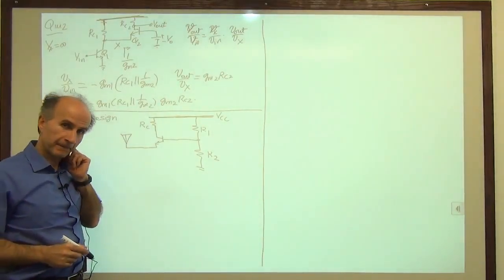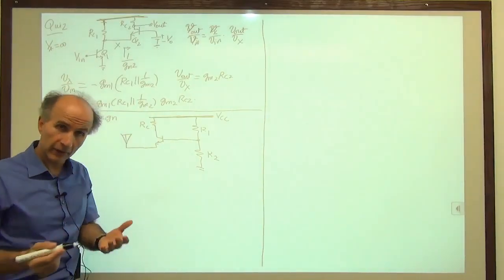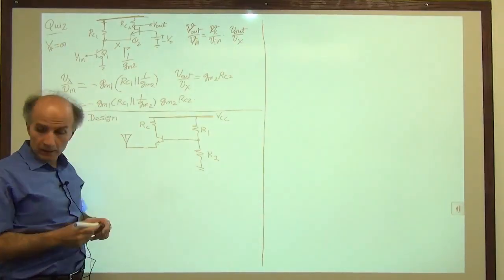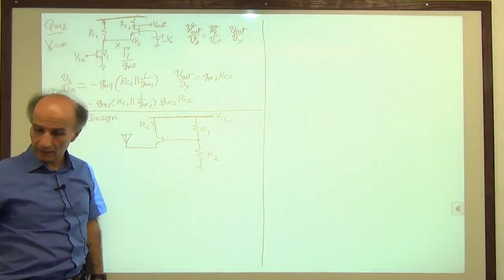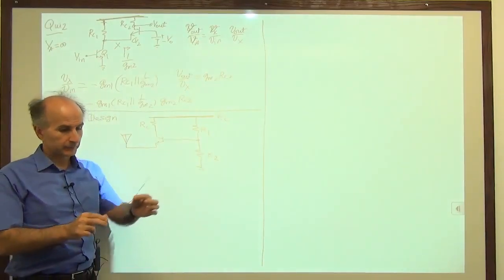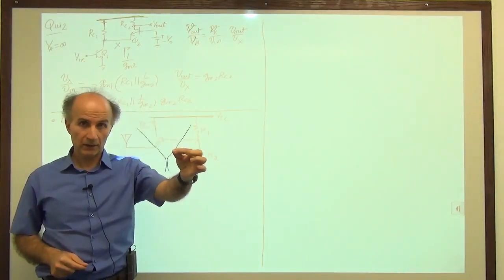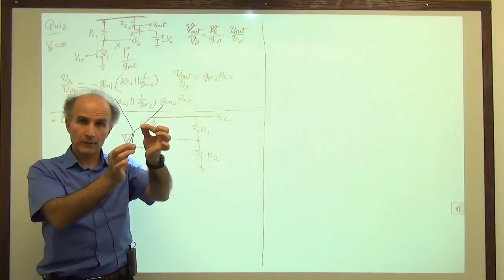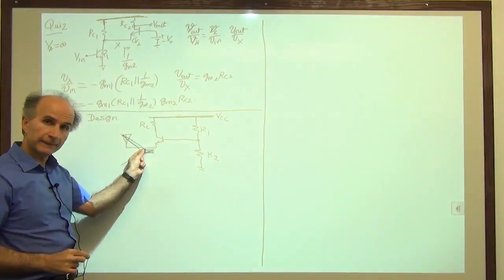All right. The question is, will the circuit work? Meaning, will the circuit have proper bias current and everything else? Well, we have to understand what this antenna is like. And for that, I can give you one example. This is called a V antenna. Oh, it looks like a V. And you can see that it consists of two conductors. And we have these two points that will be connected to the LNA input and ground. Okay. So is there a problem?